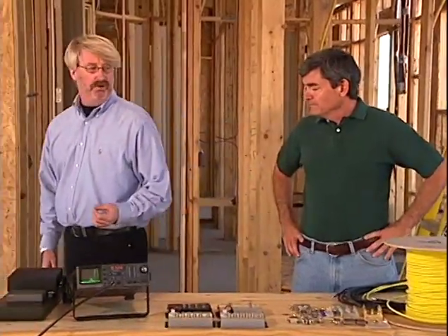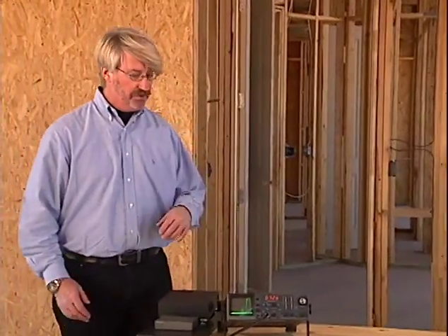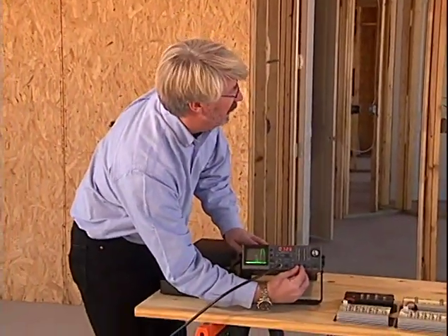Right. Now the term digital cable or digital cable channel refers to the content, not the type of channel. Exactly. Every signal on cable is analog. It's either traditional analog television or digital content on a carrier modulated with the data services such as a modem or digital television. Right. By using sophisticated compression techniques, cable companies can squeeze 6, 8, or more digitized NTSC channels into a single 6 MHz space, greatly expanding their channel capacity. Exactly. But this requires a digital set-top box that will convert the signals back into the NTSC analog.